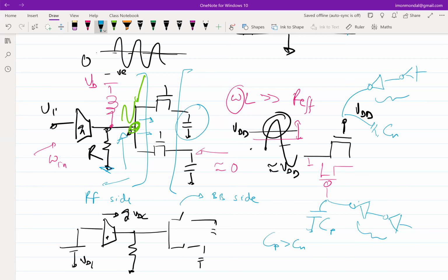So this logic is not true if the PMOS had the same strength as the NMOS. Why? Because then by adding two, it's almost equivalent to adding two devices in parallel. If I add two identical devices in parallel, then effectively the power consumption scales with Ron. If the Ron goes down by a factor of 2, power consumption goes up by a factor of 2, and there is a justification.